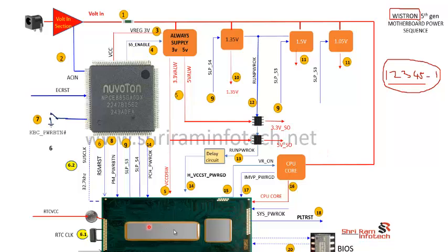First I'll introduce the board. This is the CPU, combined with the PCH, and this is the SIO. Normally in a Wistron motherboard, the SIO is by Nuvoton. These are the different buck converters. This is the always voltage, the 3 volt and 5 volt section. It's called the always voltage because this voltage supply starts before the power button is pressed.